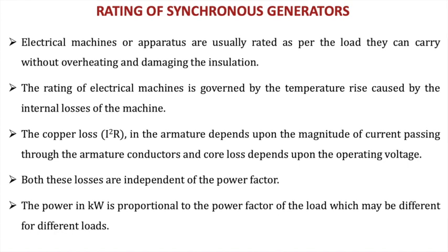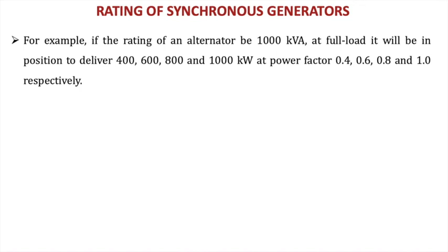Therefore, the power in kilowatts is proportional to the power factor, because the power is given as VI cos phi, where cos phi is the power factor of the load, and it depends on the load you are connecting. If it is an inductive load, the power factor will be less than 1. With a capacitive load, it will still be less than 1. The only difference is that in an inductive load the current lags the voltage, and for a capacitive load the current leads the voltage. When the power rating is in kilowatts, we are taking the power factor of the load into consideration.